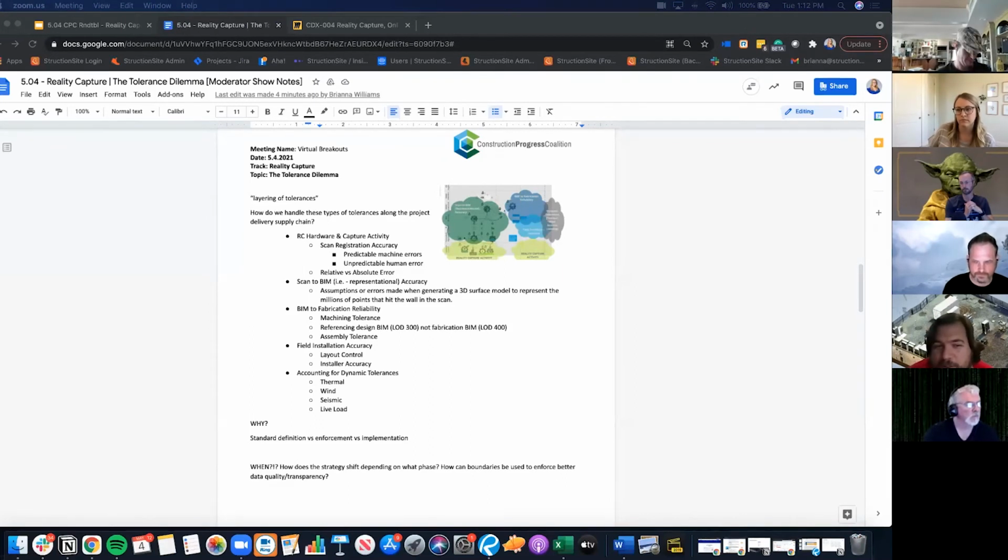But then if we're installing a feed water heater where you have spool pieces that need to fit up with weld gap being maintained, we'll use the laser tracker, maintain that weld gap and your bevels from potential cold spring if it's a mod project. And that all goes back to, like you said, picking the right tool.